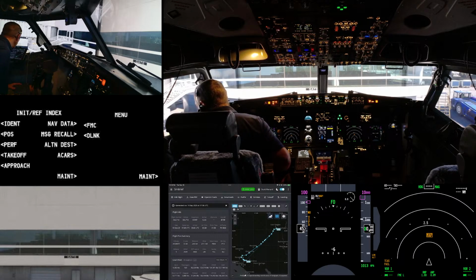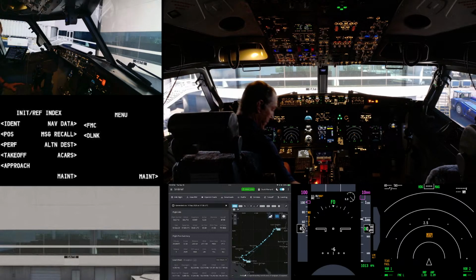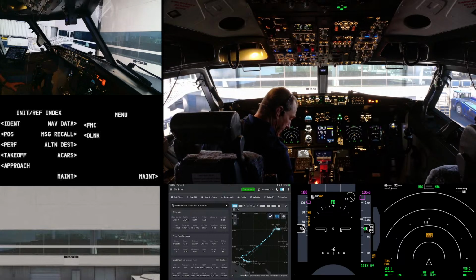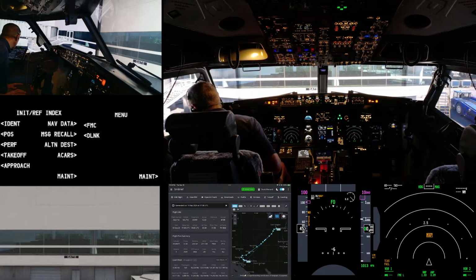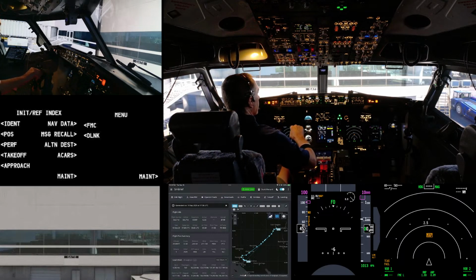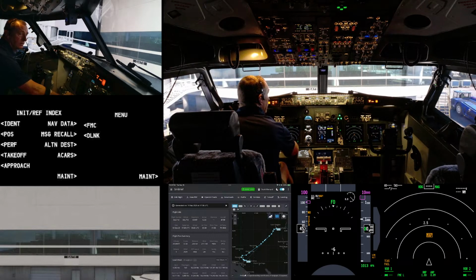Okay, so my PDC has been issued, and that is cleared via Ontario, route via the Sunshine 5 Mission departure, Rounders 4 into Las Vegas, altimeter 2990, squawk 5125. We'll put that on mode C so he knows we're here. Cleared via the Sunshine 5 departure, Mission transition, climb via SID, expect maintain 10,000. So we're going to accept for 10,000. Bring this stuff up here.